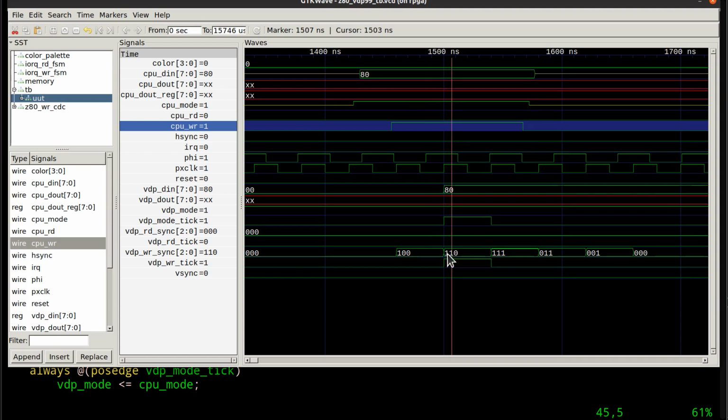And what we'll see in the logic in our code is that we'll simply ask if there's a 1 and a 0 in the right 2 bits of our shift register. That's the one and only time where we have had 2 stable reads of a 1 into our shift register. And during this window is when we want to assert our 1 tick pulse that says over here is when you want to consume the data.